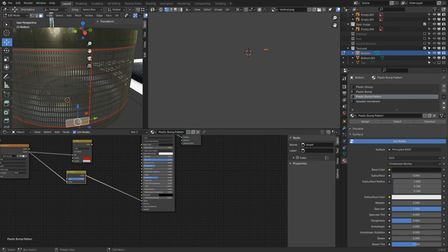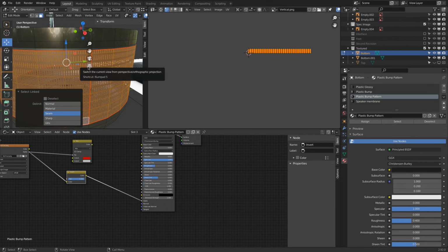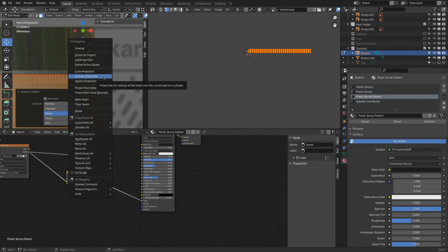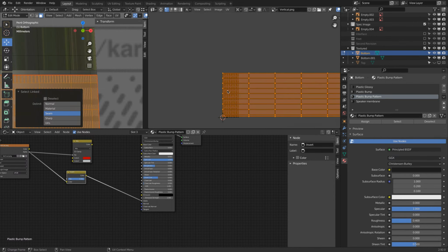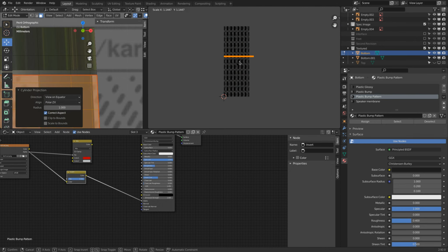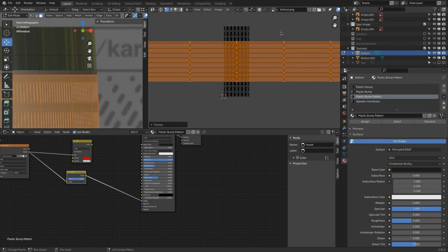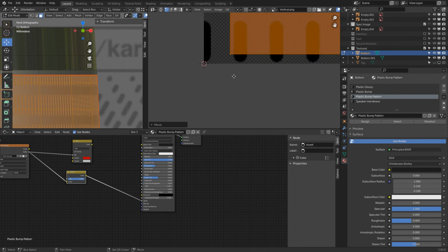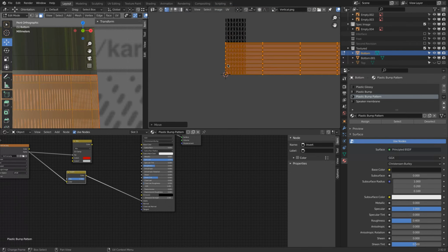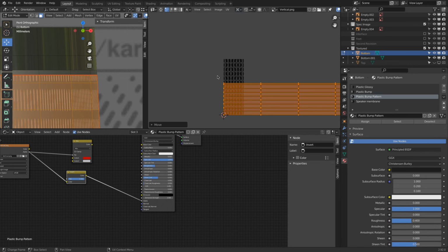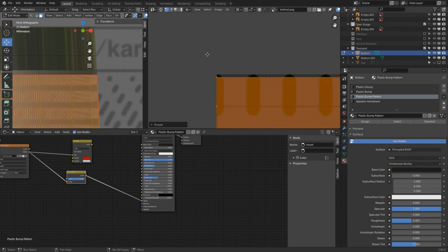And now I select this face, L, it selects all the material. I have to unwrap this one more time with the correct height. So, or no, actually, yeah, I have to U, unwrap cylinder, there we are. And then change this to this. Scale, scale, scale. We connect this to this corner. There, and then I press S. Well, we want to scale actually from the 2D cursor. You see, then it's very easy to do this.